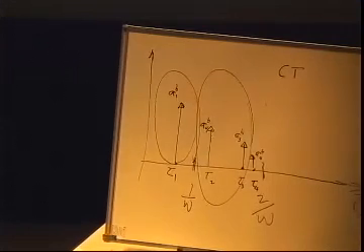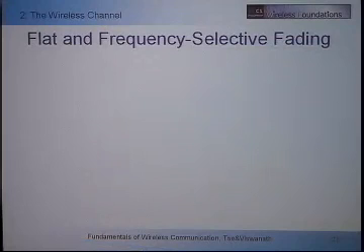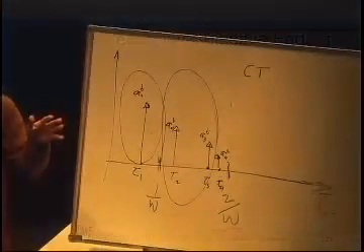Fading is an effect which depends on the fact that you have a limit in delay resolution because you have a bandwidth constraint. Why? Because if I have no bandwidth constraint, I can always see these individual paths. They never cancel each other.